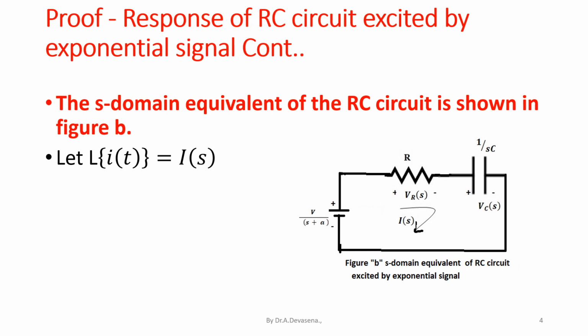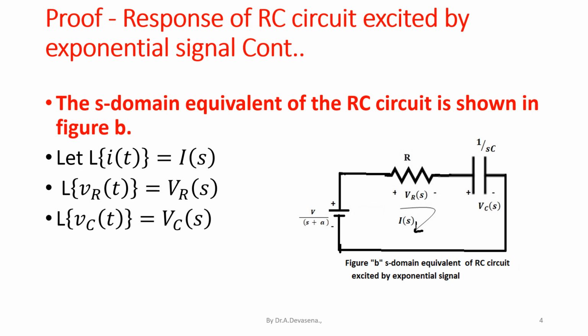Let Laplace of i(t) be equal to I(s). Laplace of V_R(t) is equal to V_R(s). Laplace of V_C(t) is equal to V_C(s). And Laplace of V into e power minus at is equal to V divided by s plus a.